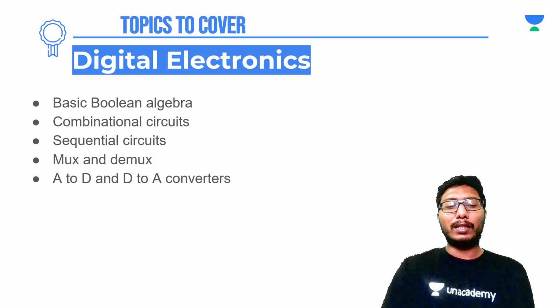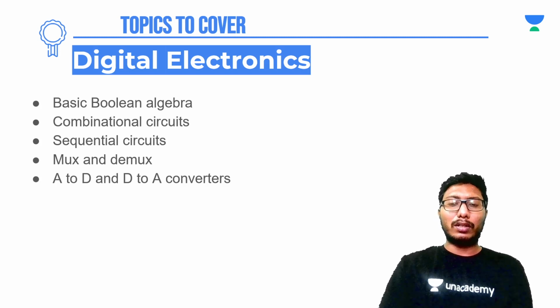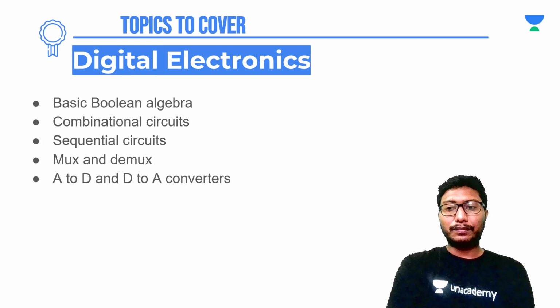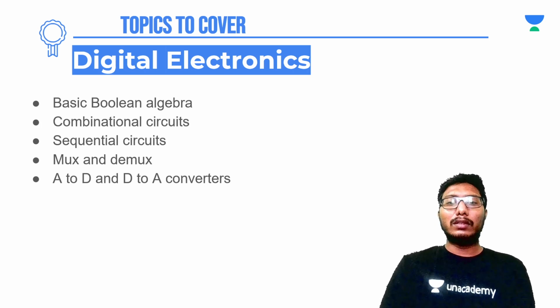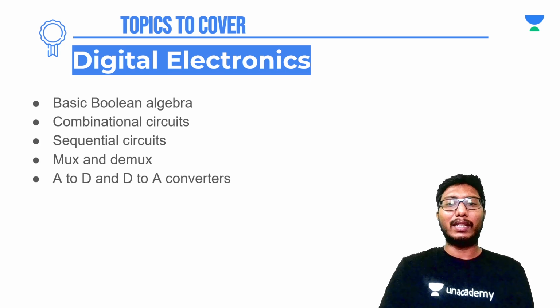What helps you in solving these truth tables is a Karnaugh map. So Karnaugh map for 3 variables and 4 variables you should be comfortable in solving. These Karnaugh maps will lead you to the output sum of products or product of sums, and also by omitting whatever common terms that you are having, you will be left with minimum terms. So you should be good with a Karnaugh map to arrive at a solution which is having minimum terms. You need not bother about the five variable one. So if you are good at solving these Karnaugh maps for 3 variables and 4 variables, then it is good. And you should know how to solve for sum of product and product of sums as well.